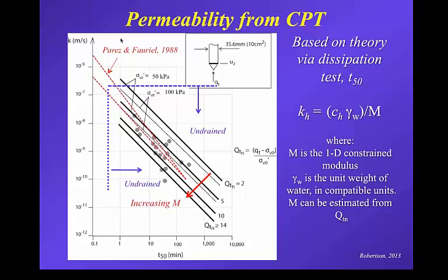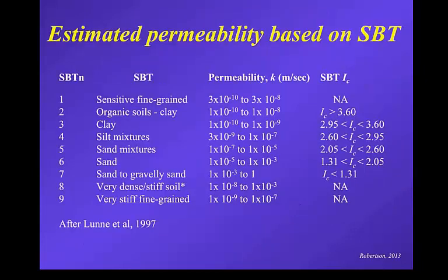And here I've marked roughly that T50 of half a minute, saying, well, this is the region where it's undrained, where it will work. Once you get outside of that, it's going to be partially drained, and the T50 won't work so well. So there's the cutoff at nominally about half a minute to a minute of T50. The dots on here are those same dots from that 92 paper, of sites around the world where people had measured coefficient of consolidation but also permeability, and so we could plot those. And you can see it fits the trend quite well.